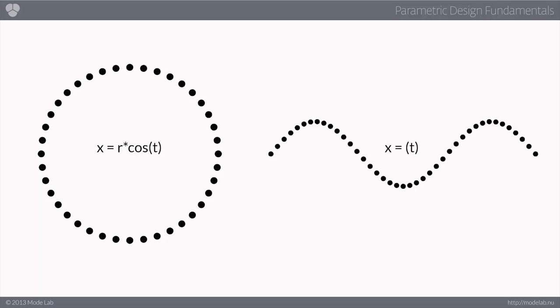So if a function is modified or a parameter is updated, the subsequent output is changed in response. And this is really the fundamental takeaway of the term parametric with regards to mathematics, is that a set of quantities are expressed by way of a function using parameters. And just to reiterate this one last time, a modification to the second equation, defining the coordinate y, results in yet another iteration of output. So here we are adding in the operator absolute to ensure that all values determined for y are in the positive direction. Absolute, or ABS, here is in bold.